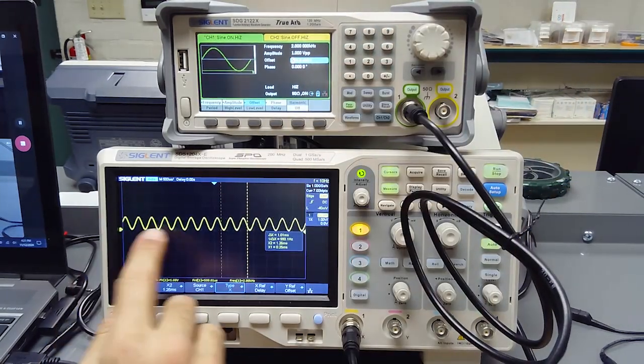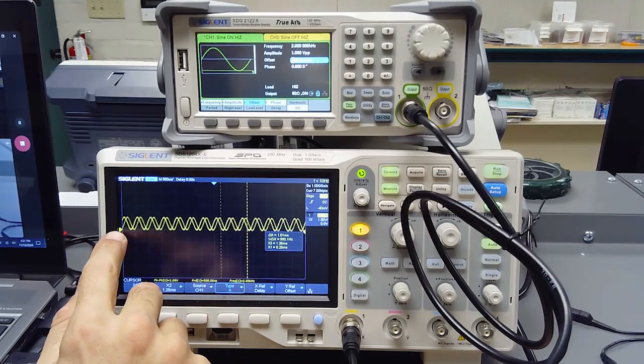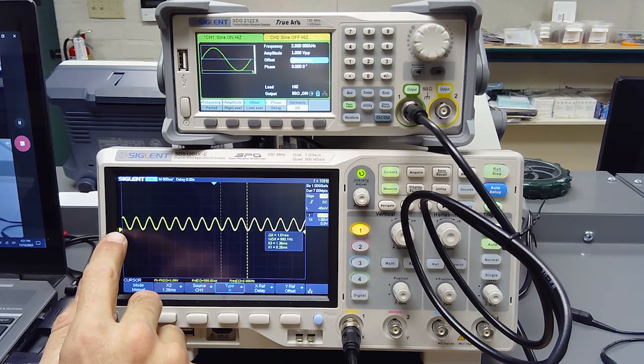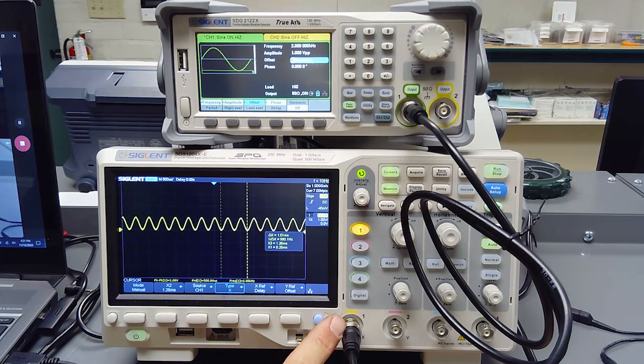Okay, now you see the bottom of the sine wave is at 0 volts, denoted by the yellow triangle, which is where your 0 volts is for channel 1. Now you might ask, why is it scrolling across the screen? It was nice and stable before. So this has to do with something called the trigger. When we have periodic waves, signals that we're measuring, anything that's periodic, it's not that helpful to look at it like this when it's moving constantly.